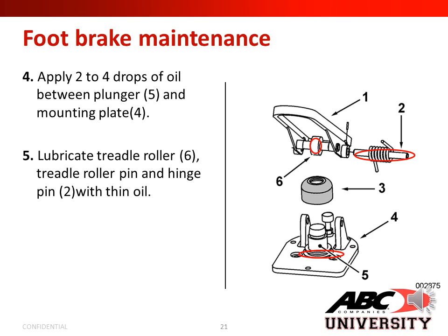Step 4. Apply 2 to 4 drops of oil between plunger 5 and mounting plate number 4. Step 5. Lubricate treadle roller number 6, treadle roller pin, and hinge pin with a thin oil. Caution: do not use too much oil when performing the foot brake maintenance.